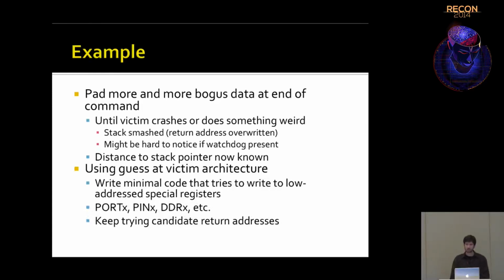But it might be hard to notice if there's a hardware watchdog that actually catches the device crashing and reboots itself quickly, so you might have to be careful about that. And now you know the distance to the stack pointer from where the beginning of your smart card command buffer goes into RAM to where the stack pointer is further down.